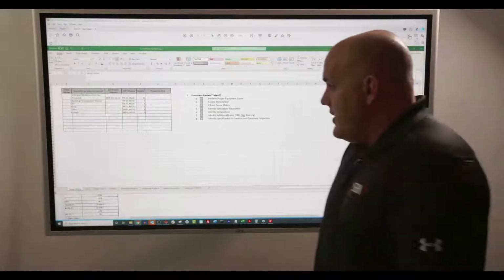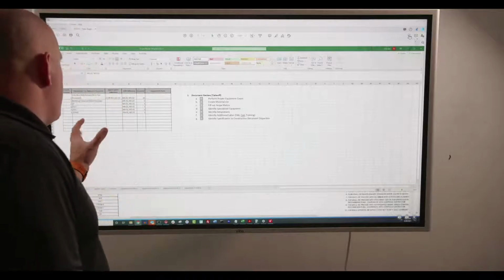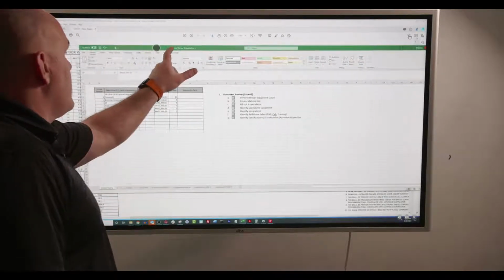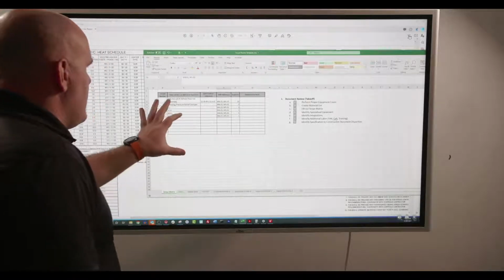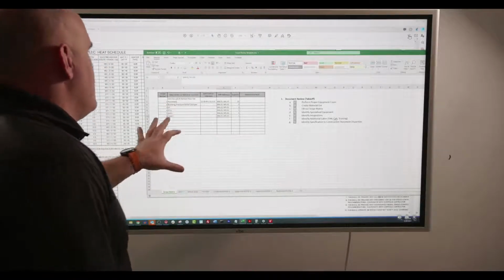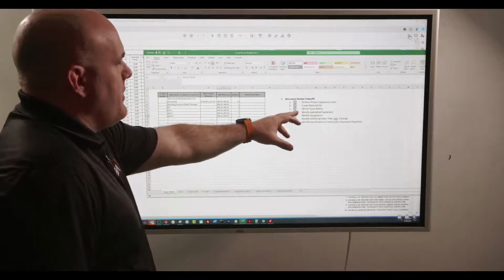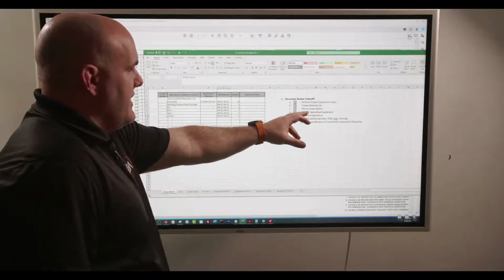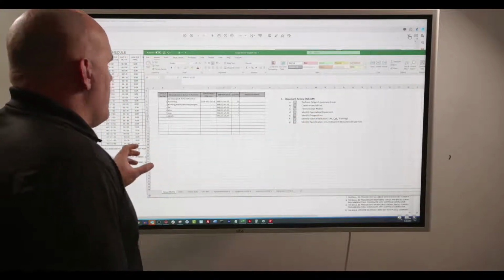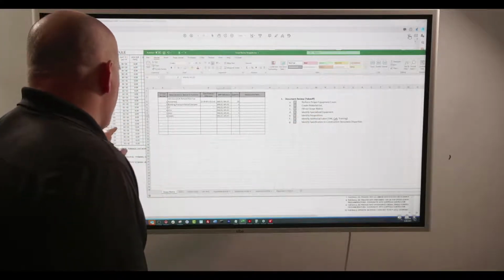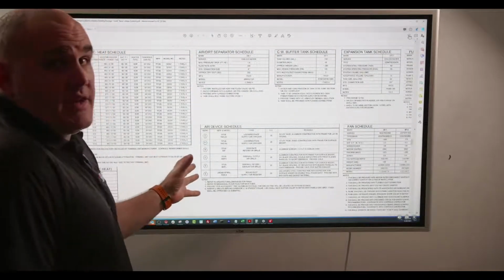Okay, so this right here is our scope matrix document. It's really small, but we have our takeoff process: perform proper equipment count, create material list, fill out our scope matrix. So in order to perform our proper equipment count, we're going to first go to what is called the equipment schedule on the mechanical drawing.